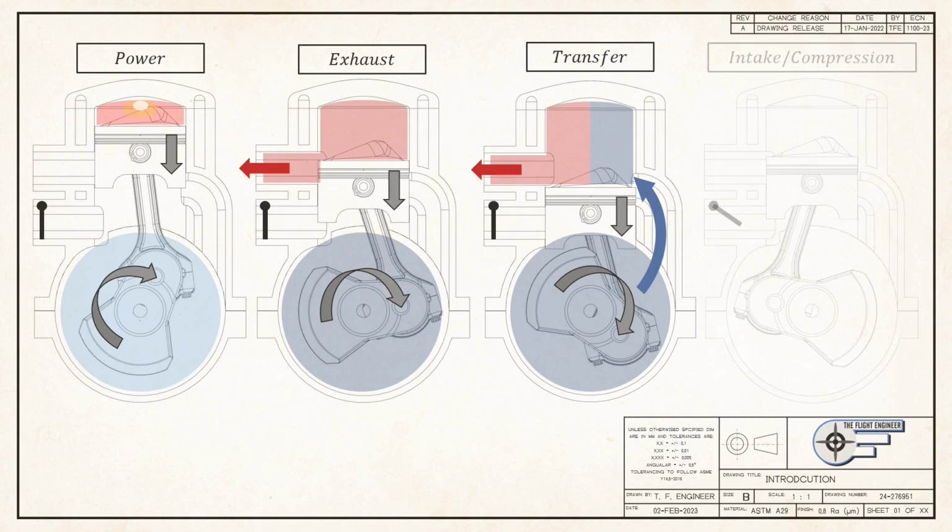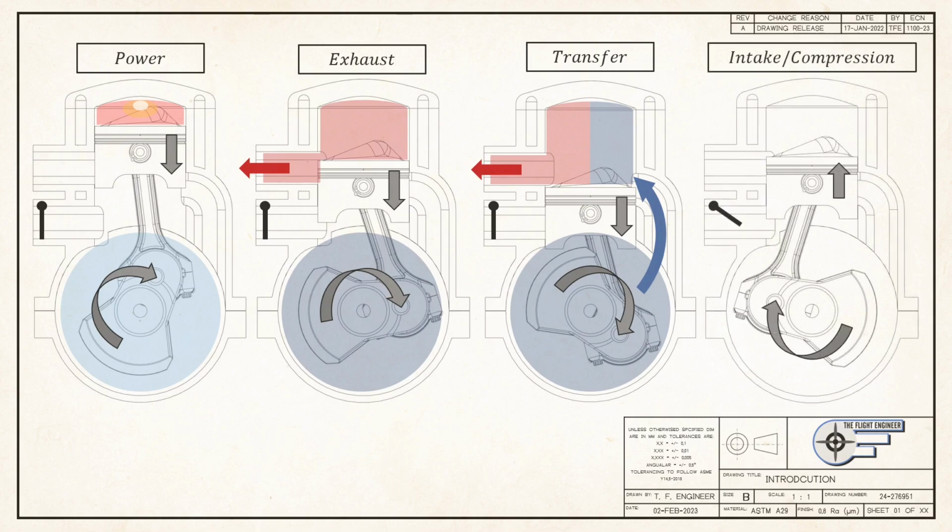As the piston changes direction and begins to move upward, the volume of the lower crankcase chamber increases. Suction opens the one-way valve in the intake port, and fresh charge air flows in. When the piston is high enough, the exhaust port is covered, sealing the combustion chamber. The charge in this upper chamber begins to compress, setting up for the cycle to repeat.